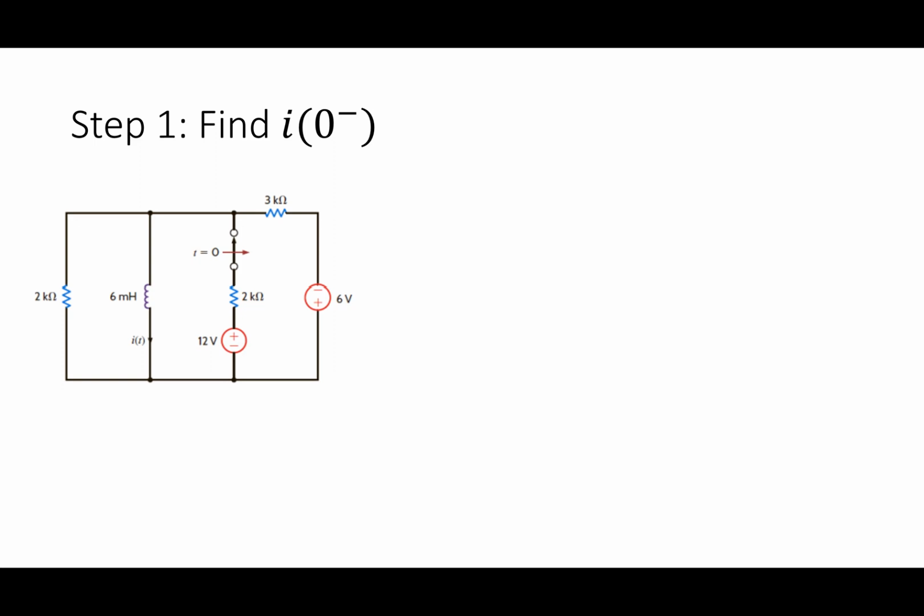All right. So in this case, what's happening at t equal to 0? Switch is opening or closing based on that picture? Switch is opening. All right. Switch is opening. And I'm saying I'm in steady state. So I want to simplify this circuit. How do I simplify this circuit for that steady state condition? What's the step that I got to make? Make the inductor a short circuit.